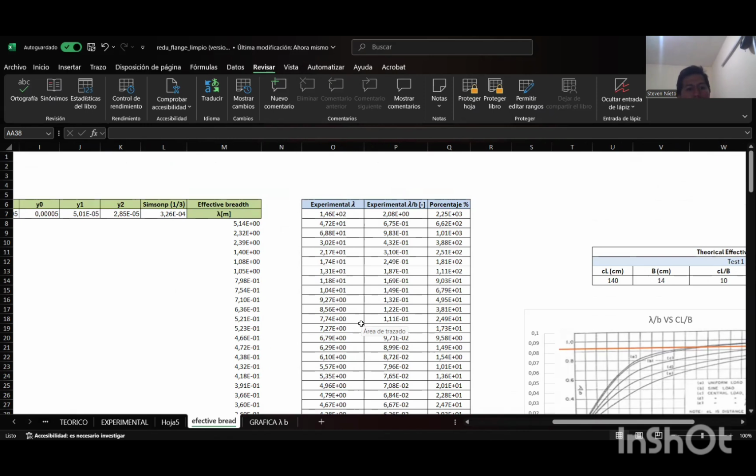The elastic behavior observed for the tests, with the aluminum remaining in the elastic range, allowed the use of Hooke's law and Mohr's circle in the analysis. The importance of the instruments: proper calibration of the data acquisition system and the load cell is essential to avoid accumulated errors, particularly when measuring small deformations. Thanks.